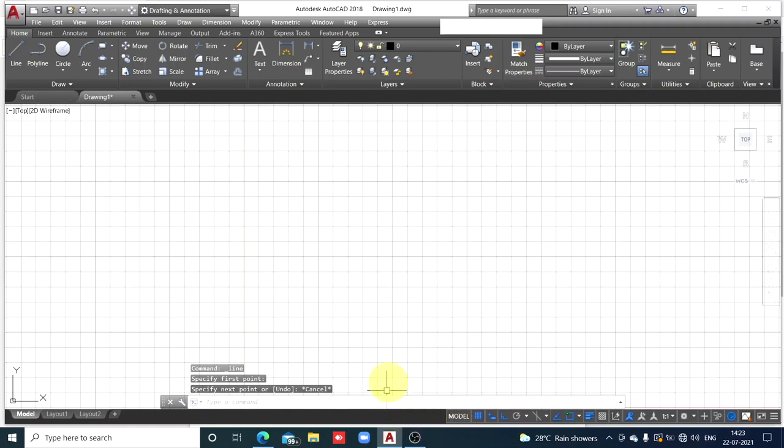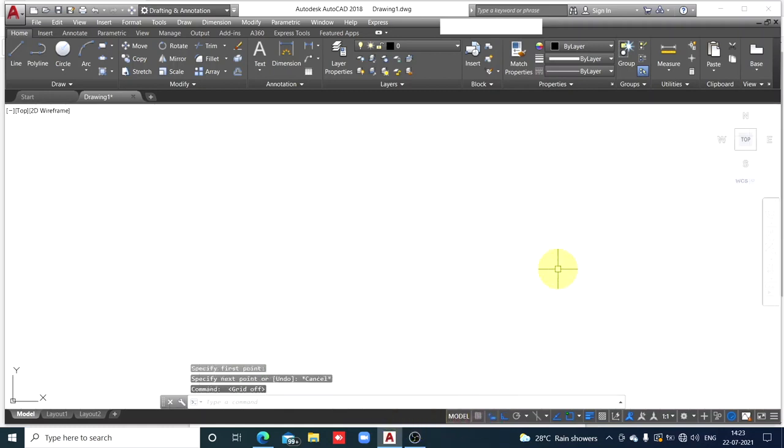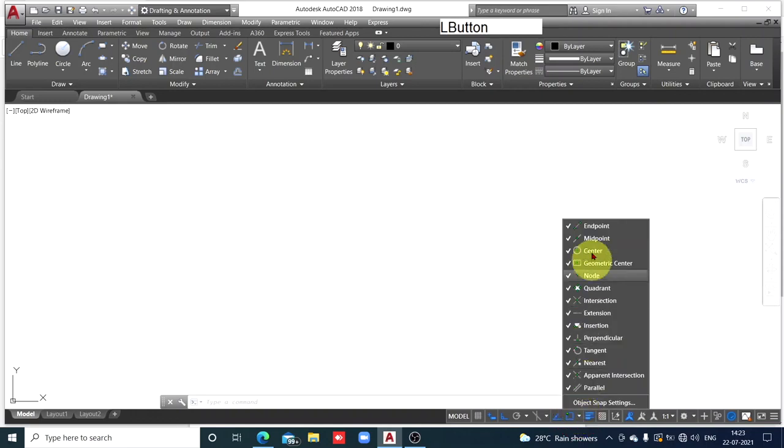Now I am not interested in grid mode, so I have closed that grid mode. These 4 toggle keys I have asked you in earlier videos also to keep on: dynamic input, ortho mode on, snapping reference lines, those green colored dotted lines you get, snapping lines we say, and snap cursor to 2D reference point. Keep it on. Check what is there in the drop down menu. Keep all these keys on in this drop down menu.